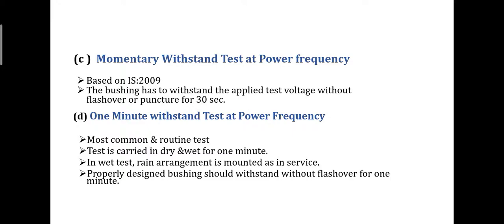Now see the 1 minute withstand test at power frequency. It is the most common and routine test. The test is carried out in dry or wet condition for 1 minute. In the wet test, a rain arrangement is mounted as in service. Properly designed bushing should withstand without flashover for 1 minute.